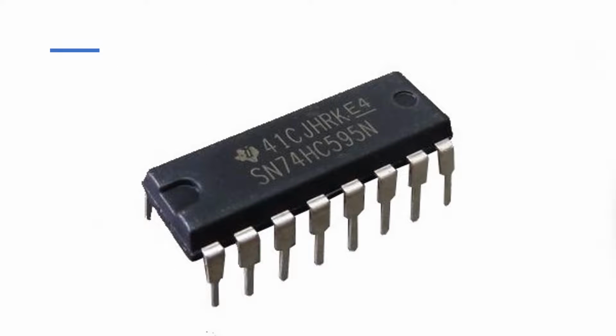Okay guys, so looking at the register here, SM74HC595N, a very common form of register. This one can be used for both serial in, parallel out, and in case you can also use it as serial in, serial out. This comprises 16 pins.